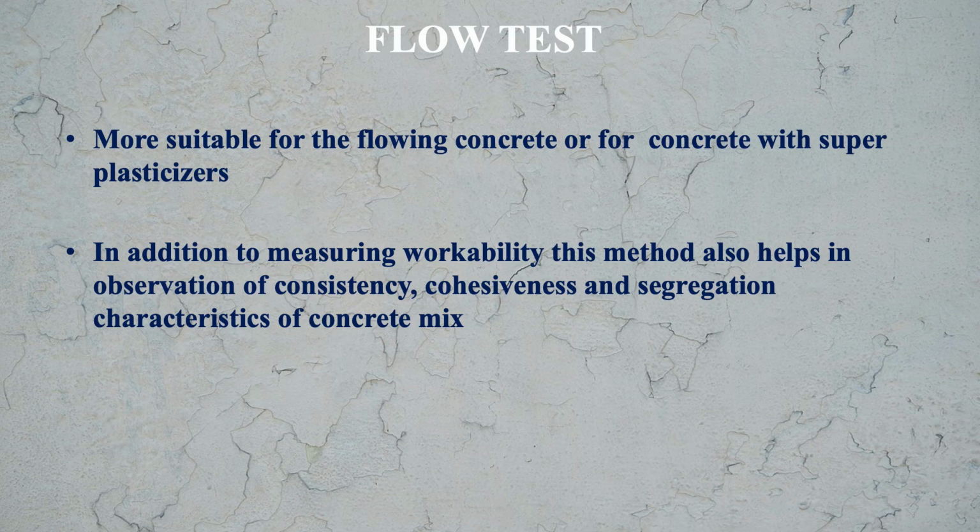In addition to measuring workability, this method also helps in observation of consistency, cohesiveness and segregation characteristics of the concrete mix. So in addition to measuring the workability by this test, it is possible to observe three properties of the concrete mix. What are these three properties? Consistency of the concrete mix, cohesiveness of the concrete mix and segregation characteristics, if there is any possibility of segregation of the concrete mix. These things you can also observe with the help of this test.